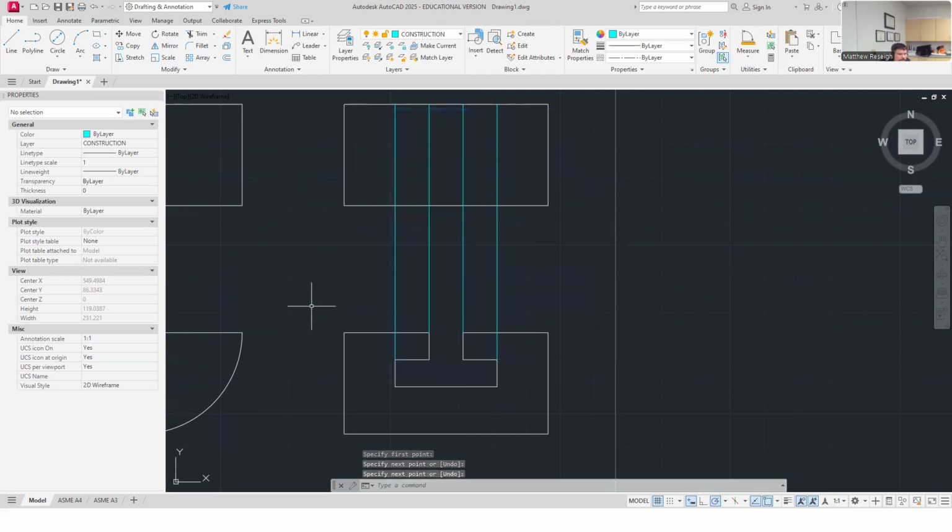I like the thought process of considering when surfaces appear as a line, right? Because that is a concept of orthographic projection. The front surface appears as a surface here. It appears as a line in the top view. The little depth slot here appears as a line here, this surface of maybe how deep this is. It also appears as a line here. So in order to show the surface, like the way I'm pointing at that, I would need to show that in the right side view or the left side view.